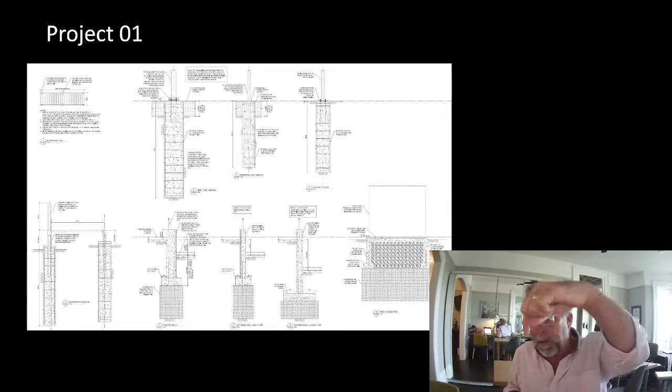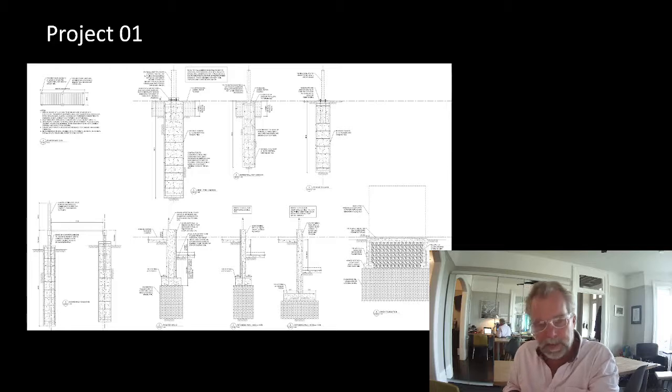I just said water can't get in from above because it's a slab. Do not ever believe that a slab is waterproof. Slabs are not waterproof. Concrete cracks, and water finds its way through. If you need to prevent water from getting underneath something, you need to put a membrane on it.